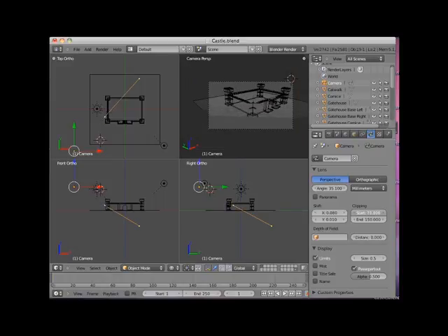I can also adjust the end clipping, which is the distance in Blender units from the camera object when the camera stops seeing objects. It is now set at 150. As I lower this number, the camera extent view is reduced. Notice in the camera view what happens as the end clipping point enters the building model. Now by default, Blender sets this end clipping to 100.